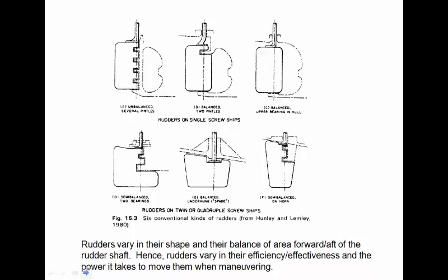We have some different types here where your propeller would actually be housed inside of these. These are good. There's nothing wrong with them. They put the propeller right in line with the rudder, and they have a lot of surface area. They also create a lot of drag and a lot of non-laminar flow of the water into the propeller because of all the housing that's around it.